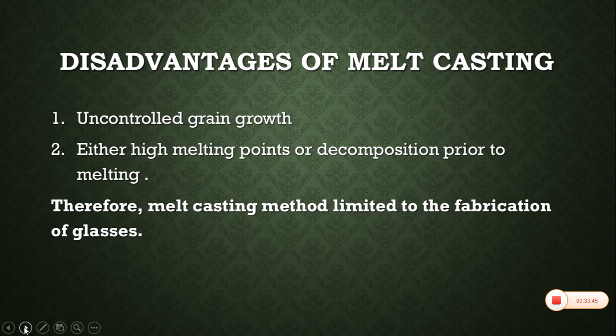By using this method, these high temperature ceramics decompose prior to melting, or it is very difficult to obtain a melt of these high melting temperature materials. So the melt casting method is limited to the fabrication of glasses.